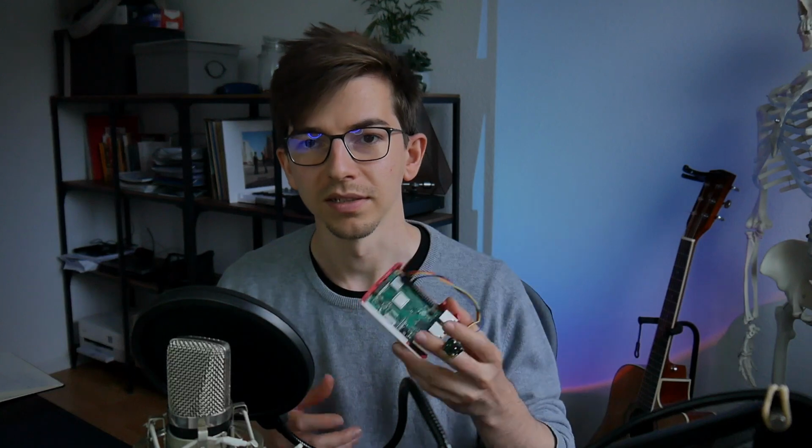And in this video, I'm gonna cover writing a driver for the Raspberry Pi UART interface. So we replace that QEMU output thing with a real hardware UART interface, and even more, booting the Raspberry Pi with our custom operating system. It's kind of a kernel, not a real operating system, just a kernel running on it and putting some text out on the UART interface.